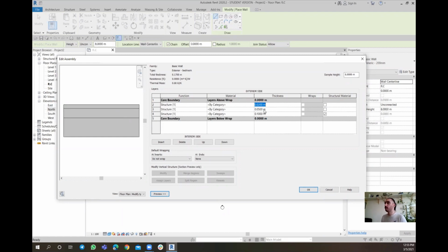So for that reason, I would stick with this 5 centimeters thickness for the back one. Then I'm assuming that layer to be a structural part of the wall, meaning that it would be assigned to the masonry brick that we're having on our project, right? So the masonry blocks, those sort of blocks should be getting assigned to that. So this is mortar, this is tile, this is the wall masonry bricks or blocks that are getting there.